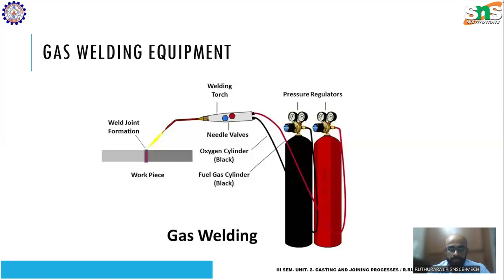So imagine when the gas is depleted inside the cylinder, there is low gas inside the cylinder. What happens? Automatically, the pressure outside will be higher than the pressure inside, and the air tends to get inside. If that happens, fire will go inside, and if it goes inside, then an accident may occur. So to prevent this, the pressure regulators are fitted with equipment called a non-return valve, which is controlling the flow in a single direction only. What it means is that gas can only come outside. It cannot go inside. If it tries to go inside, it will be arrested.